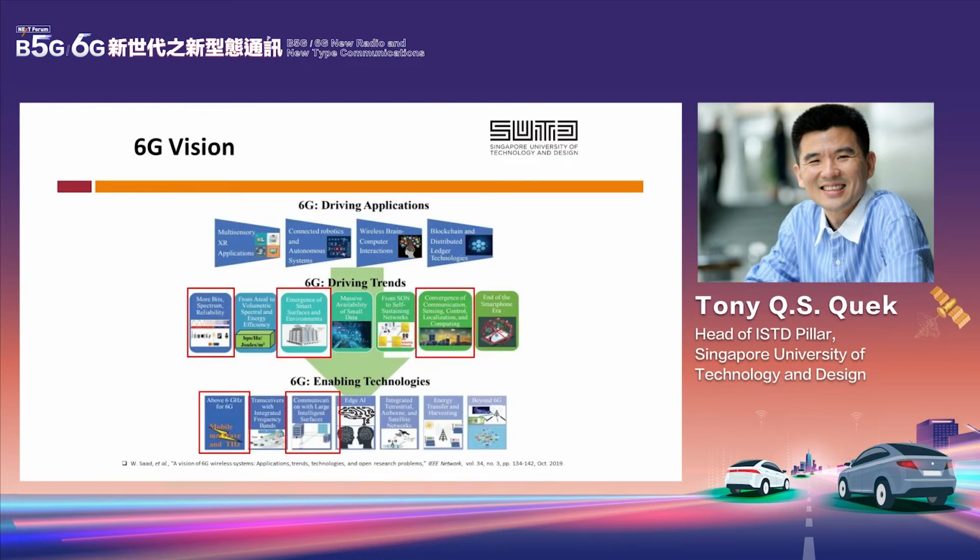So as we move from 5G to 6G, and we look at the 6G vision, there are a few technologies we see. It's a continuation of what we see in 5G, where you want to exploit the spatial domain and the frequency domain. One is more spectrum. You want to have more bits, and you see that in 6G, there's a push to go beyond the millimeter wave spectrum, up to even 100 gigahertz, terahertz. At the same time, you look at the antenna elements. From massive antenna elements, now we go to large intelligent surfaces, where the whole concept is increasing the spatial domain.